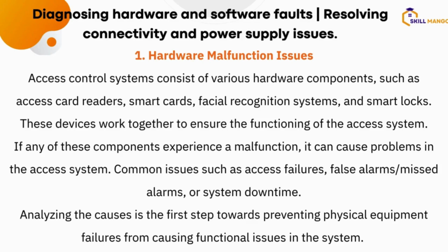You have to understand all your devices' power ratings and power requirements: your maglock, based on the brand you are using, your exit button, your readers, the kind of cable you use. All the components you are using together, you know their power rating. You now combine all this together. This will advise you on the kind of power supply to deploy, to avoid hardware malfunctions or issues.